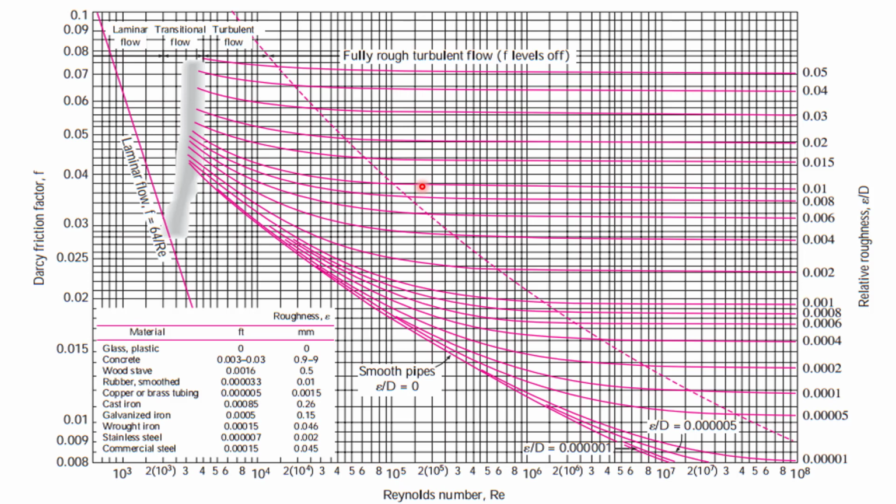The Darcy friction factor can also be found from this Moody chart. This chart is used by engineers to find the pressure drop in pipes for turbulent flows and laminar flows. This straight line is for laminar flow, which is independent of the wall roughness, and it can be found by a simple relation f is equal to 64 divided by Reynolds number.